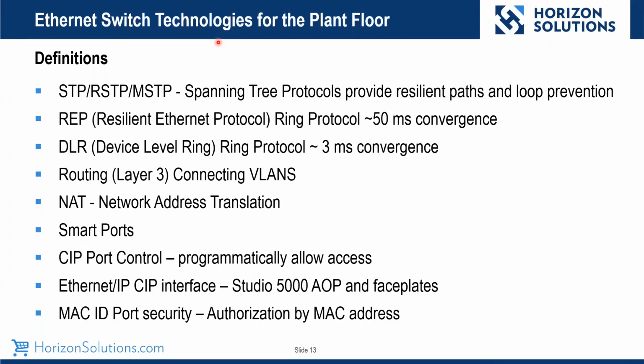What Rockwell brought to the table when we partnered with Cisco is these things called smart ports. Smart ports are macros that run based on the traffic that you're configuring. When you configure the switch, you click on the port and say, I want this to be an automation device, or another switch, or a wireless, or a PC. It'll configure all those CLI commands for that port. So it gives a controls engineer the ability to configure these switches without really knowing the whole language of the CLI. It's a really nice way to do it.